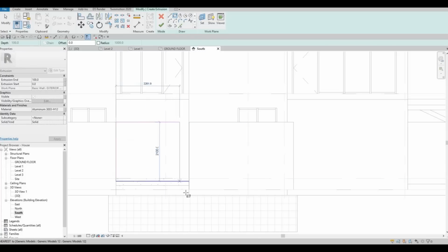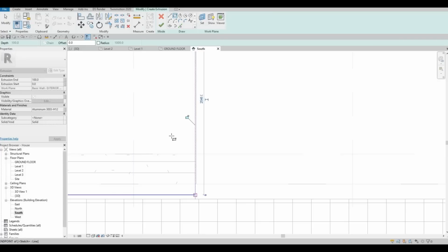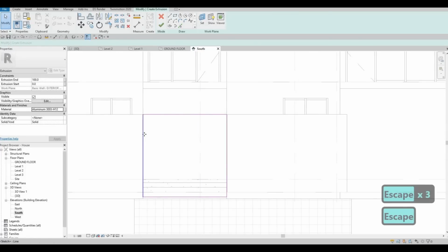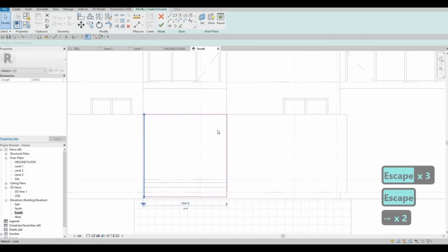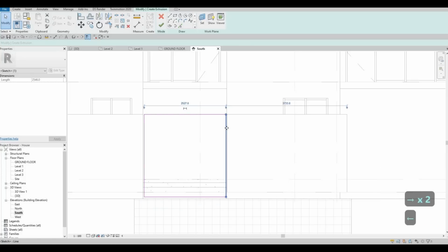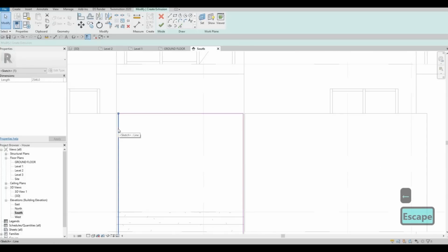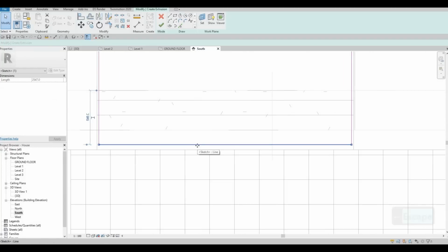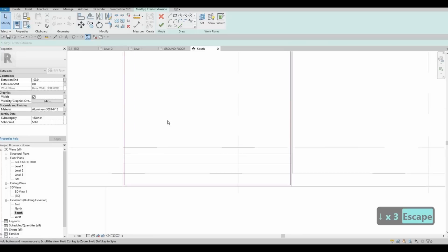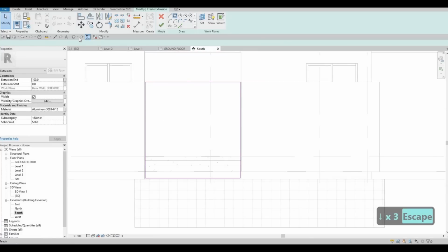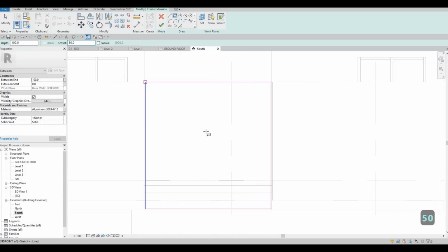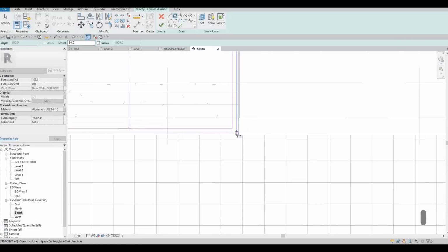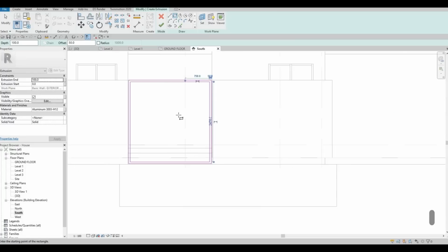and then obviously we need to add rectangles right here. And then before we do that, we need to select here and then nudge it a little bit on the side. The reason for that is obviously we have some hinges there, so I don't want to give it too much of that without a gap, so that's why I'm doing this, to make it look realistic enough. And then here we could offset this to probably 50, and then press spacebar in order for your offset to go inside. After that, click on finish,